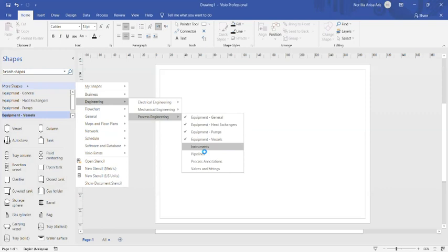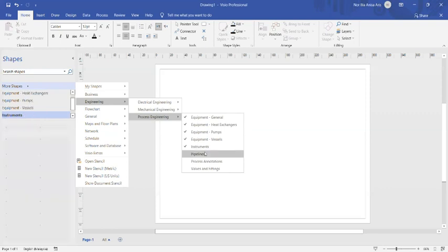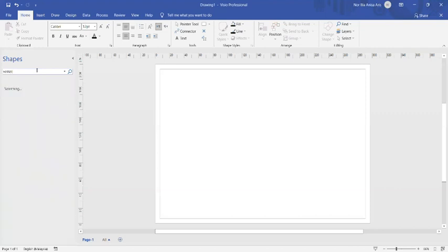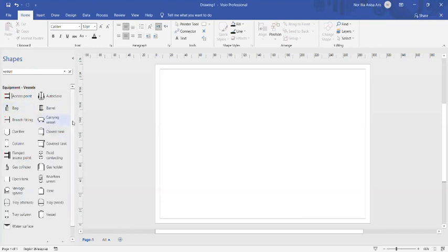The first step in producing a PFD is to identify the equipment in your process. After that, we are going to drag the equipment first before we connect the equipment via the pipeline. From the example, we know that the equipment we have is a reactor. The reactor is categorized under vessels. So just type vessel here and then scroll down to see more results.